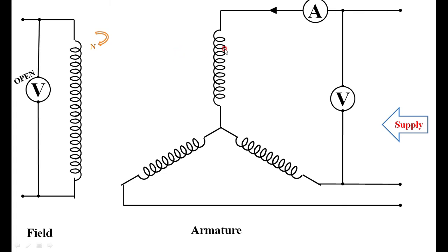When the reactance is Xq, which is less, the current drawn is more, because if you neglect the resistance, I is equal to V by X. The applied voltage V remains the same, but with Xd the reactance in the denominator is more, therefore the current is less. So you note down the deflection of the ammeter, a maximum and a minimum value.